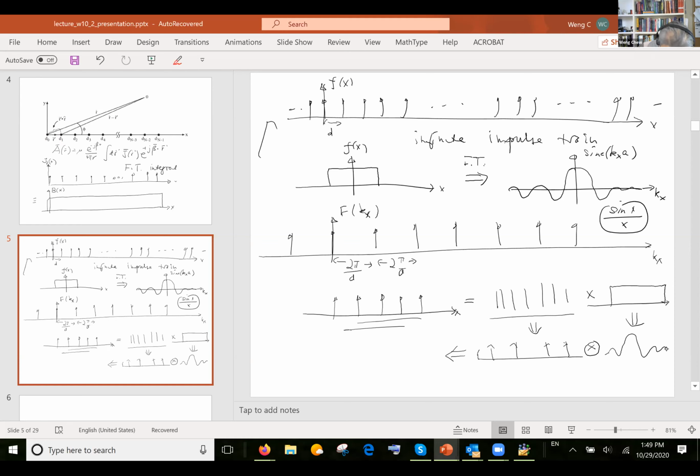If you convolve these two together, you get a sinc, and then a sinc that repeats itself, and then a sinc that repeats itself. You get a digital sinc when you Fourier transform a finite set of sources.